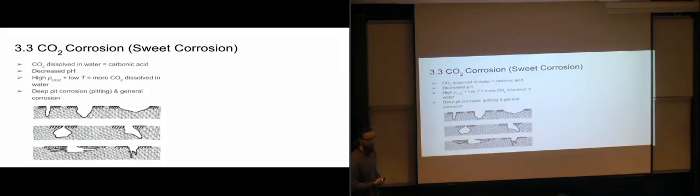That's very bad. So you really don't want that to happen, because you never know exactly how deep it's going to go. And since it goes deep into your material, it's also going to affect the strength of the material. For example, the wall thickness of your pipeline can be affected by the pitting corrosion, and that's going to make that section of the pipeline handle less pressure.